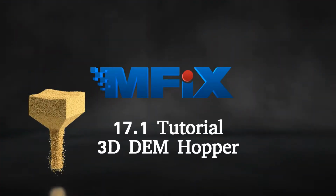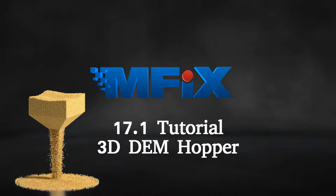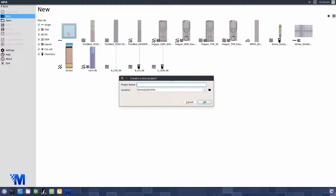In this tutorial, you'll learn how to set up a 3D DEM simulation of a hopper. First, create a new project by going to New on the main menu and selecting the blank template. Enter a name for the project and select a location to save to.